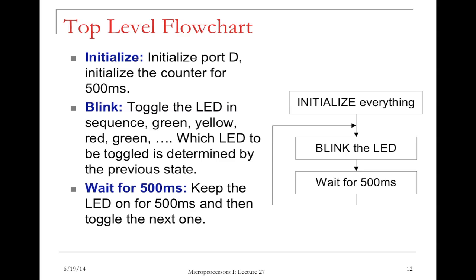So after you toggle that LED, so you switch from green to yellow, then you need to wait that 500 millisecond or half second. That's where you will call the 10 millisecond subroutine for 50 times. And once that's done, you will come back to do the blink again.